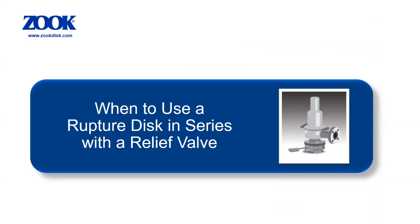A certified CCF for a specific disk and valve combination can be derived by actual flow testing. This will typically give a higher CCF, meaning a lesser derating of the combination. Caution is advised not to rely on a high certified CCF value. Doing so will limit flexibility if changes to the rupture disk or pressure relief valve are required in the future.